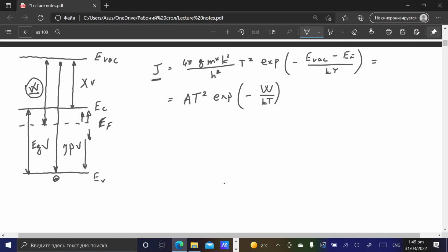So it would be good to define the work function for different cases: for intrinsic semiconductor, for p- and n-type doped semiconductor. For an intrinsic semiconductor, we can write that it is the electron affinity plus 1/2 of the band gap, because for an intrinsic semiconductor, if we show it here, EC, EV, this is the middle of the band gap, Ei, for an intrinsic semiconductor.